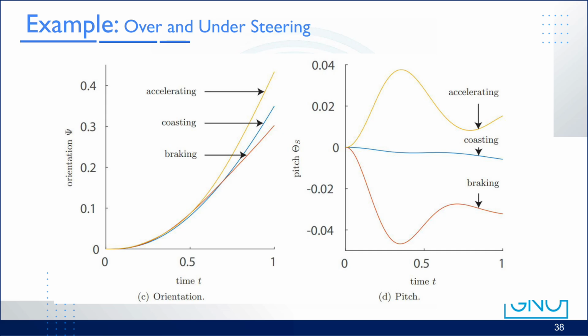When the car moves straight, the yaw angle is 0. A positive yaw angle means the car has rotated counterclockwise, or to the left. A negative yaw angle means a clockwise rotation, or to the right. The yaw rate, spoken as psi dot, tells us how quickly the heading is changing over time. This represents how fast the car is turning on the road.